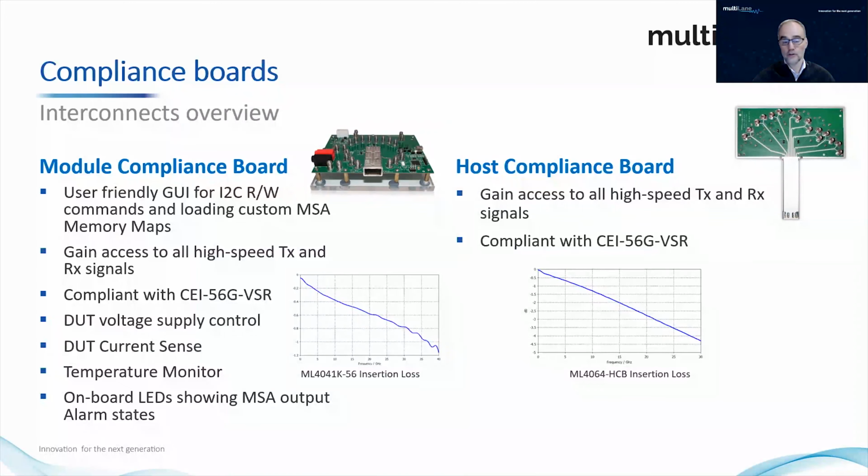So let's talk a little bit about loopbacks. What is the best way to validate the proper operation of your system port? If you plug in a transceiver, is it recognized? Is the CMIS compatible? Is the signal integrity sufficient? Or can your system support the intended thermal and power load? So basically, we developed loopbacks or thermal loads that are emulating the more costly optical transceivers.